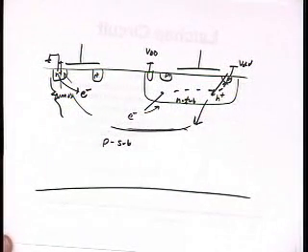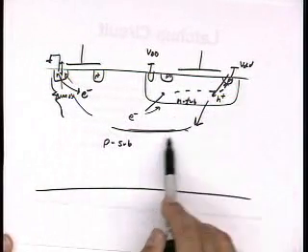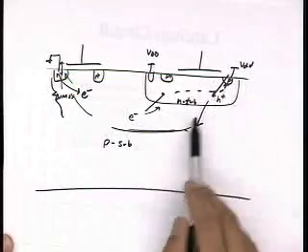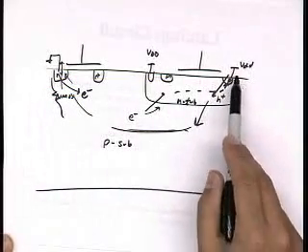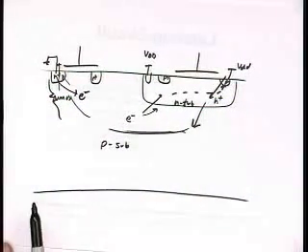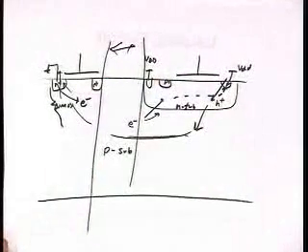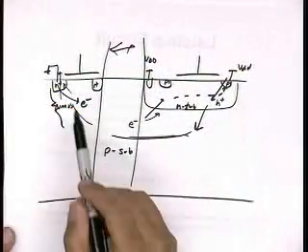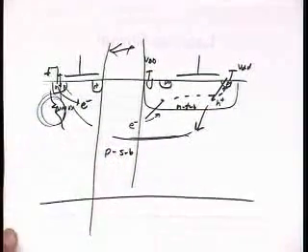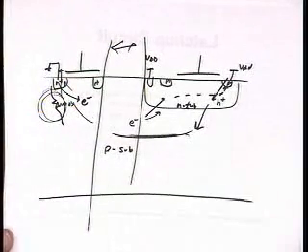I have positive feedback. A couple more electrons here, do the same thing. A couple more holes. Now a few more electrons. Now a few more holes. And it just keeps going back and forth. And eventually I've got a dead short from VDD to ground. So that's how latch-up happens. And that's why this distance is so important in preventing latch-up. And that's why the resistivity is also very important, because the more resistive the substrate, the more voltage drop we get with minority carriers flowing.